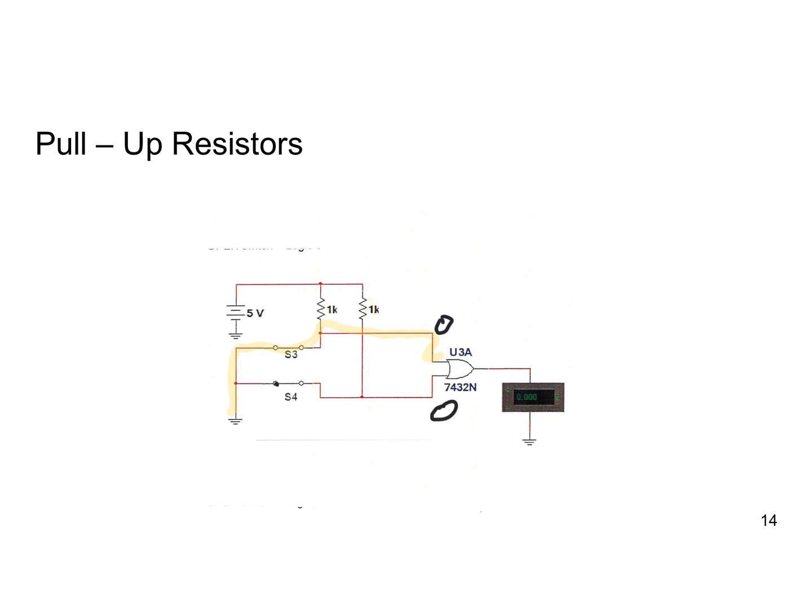If we then open the switch like that, we see a direct connection from here up to the 5 volts. So this is going to go to a logic 1. So either pull up or pull down resistors must be used. Again, depends on the application.